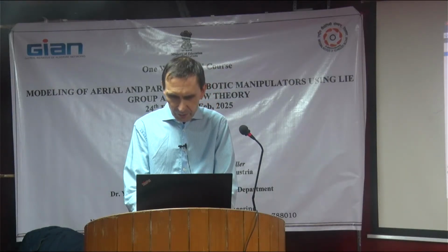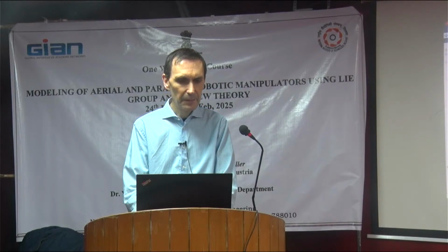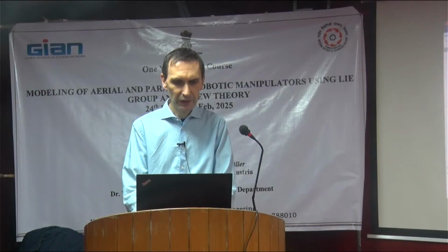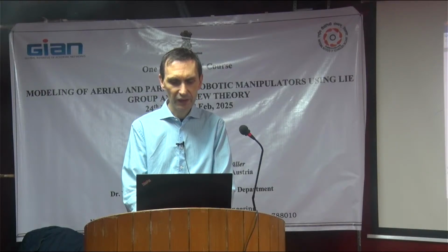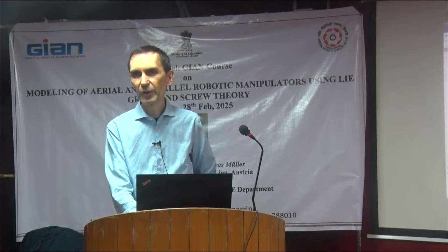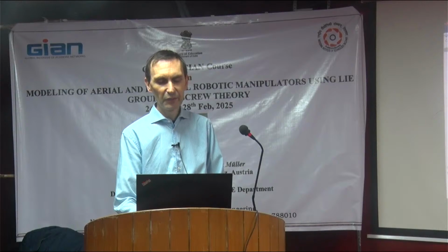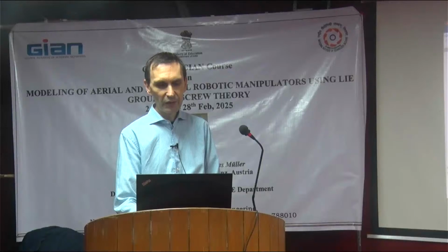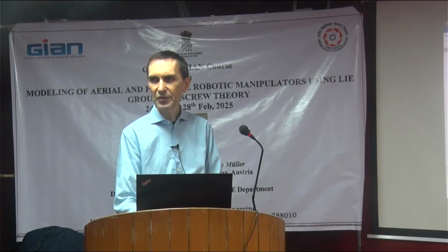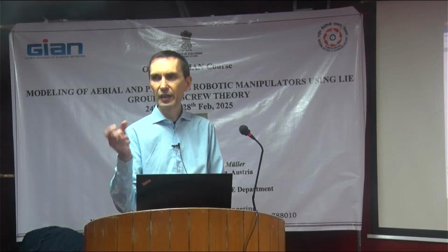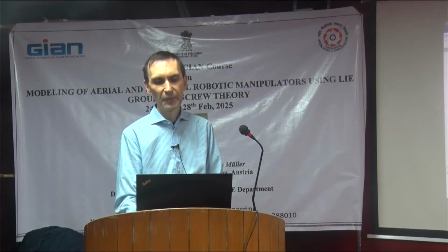Maybe the planar 2R, the one that we just had. By the way, MATLAB can also do symbolic computations. It's not perfect. For symbolic computation, you better use a different package. But you know how to do symbolic computation in MATLAB? So we have the parameters L1, L2, the lengths, and the joint angles Q1, Q2. And I just say these are symbolic real numbers.